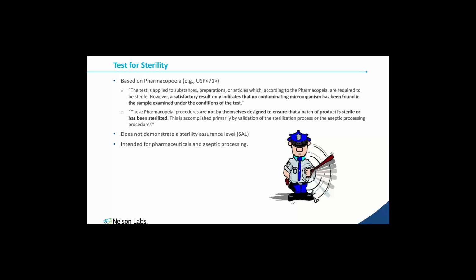So the sterility is being maintained rather than being performed. Terminal sterilization, quite simply, is terminal. It's at the end. What does that mean? I'm sterilizing the finished product in its sterile barrier system, in its packaging. So terminal sterilization is done at the end. In aseptic processing, I have steps leading into it that have to be sterile, and I'm maintaining that sterility.